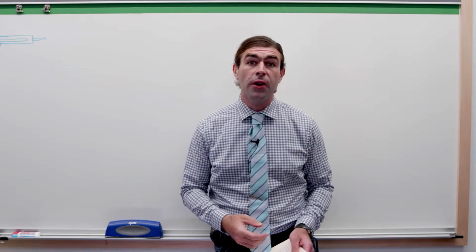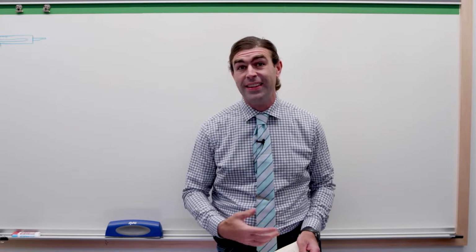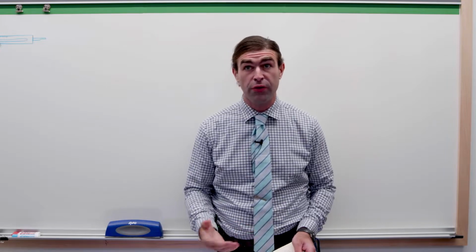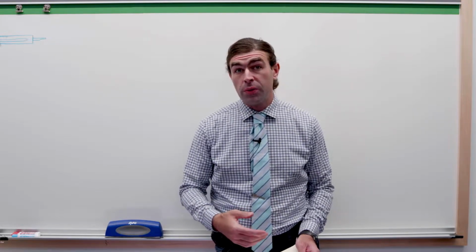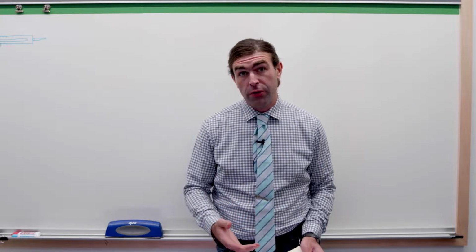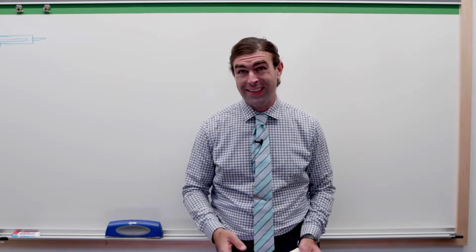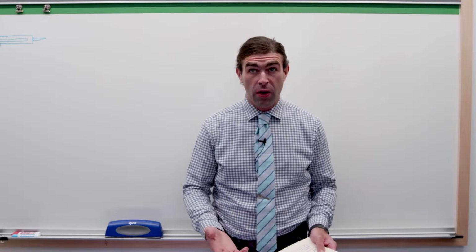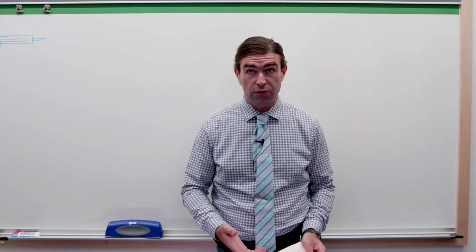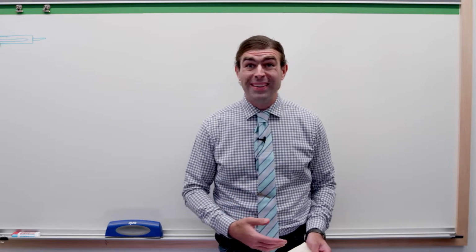In this video, I'm going to talk about a couple of advanced GD&T topics that you need to know for the certification exam and for design in general. So the topics are inner and outer boundaries and virtual and resultant condition, and specifically how to figure out what they are on a given feature on a given drawing.